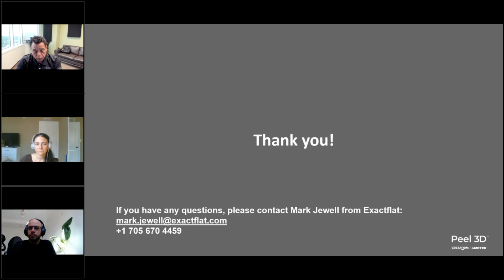So we have a lot of experience with this. The training programs that Gonzalo has put together, they can show you how to process your files, work with ExactFlat to get your patterns to fit perfectly every time. The underlying object that you're scanning is what will be used to generate your patterns. So if you want a different set of patterns that doesn't conform to that underlying object, you're going to have a mismatch. Just keep in mind, the scanner will pick up exactly what it sees, and ExactFlat will convert exactly what is in that 3D model prototype.